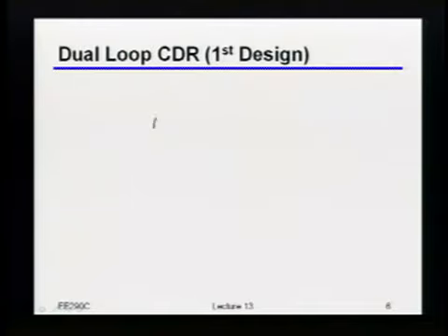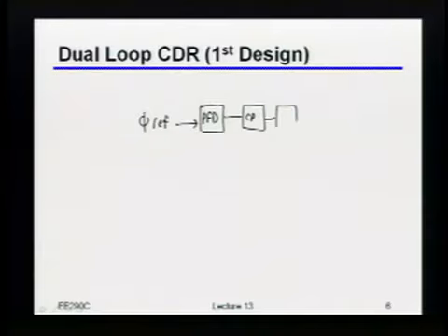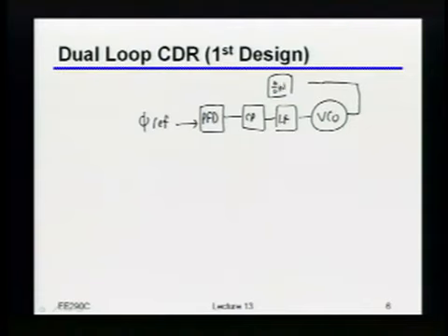Basically now I really am going to take some reference. This is going to be some frequency reference, but hopefully a clean frequency reference. And with that, I'm going to build pretty much a traditional PLL. I'm going to have some PFD, some charge pump, some loop filter, some VCO. I'm going to take the output of that VCO and feed it back through some divider.